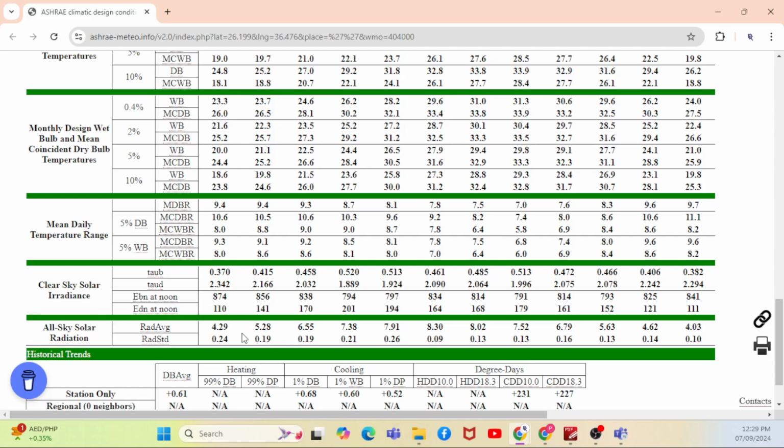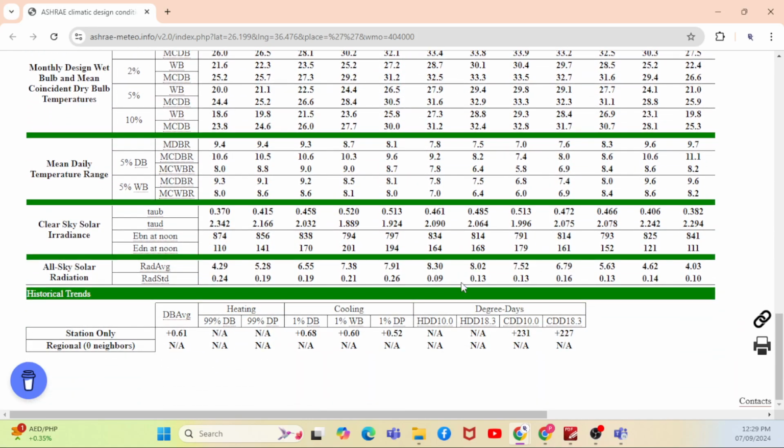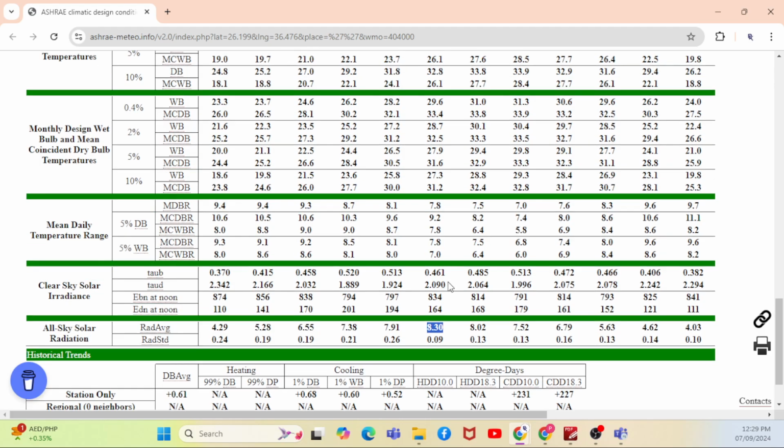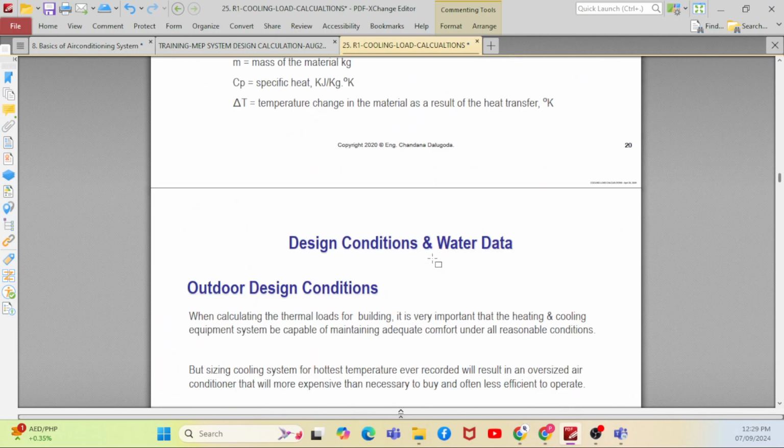So you can see that, for example, during the month of June, you can see very high intensity from the solar, right? Correct. So this will vary depending upon the month, and also it will vary depending upon the direction, and also depending upon the timing in the same particular day. For example, in the morning you can go outside, but in the afternoon you cannot go outside because it has high intensity, right? So the same heat intensity will affect your heat load as well.